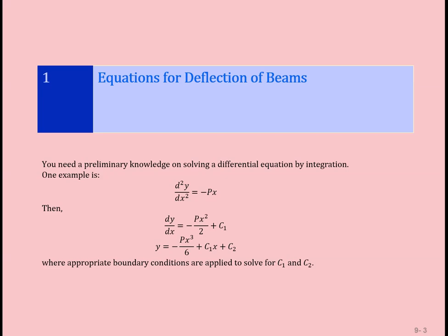To proceed, you must have knowledge of solving differential equations. Here are ordinary differential equations, solved by integration. The example I give here is highly relevant to what we're going to see in the deflection of beams. For example, we look at the second order differential equation d²y/dx² equal to minus px.